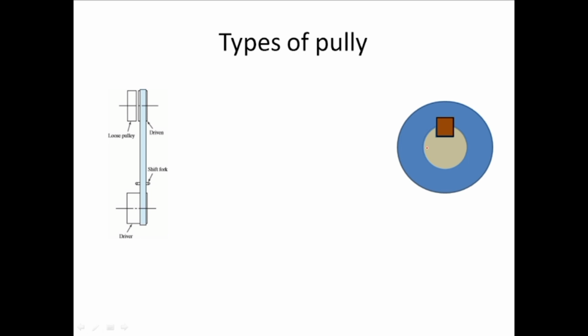After insertion, let's say when this shaft rotates in this direction, it will exert a force on this coupling key to rotate with itself, and in return it will exert a force on this pulley to rotate with it. So the pulley will rotate, and if this pulley is rotating in this direction, it will exert a force on this coupling key, which in turn will exert a force on this shaft, so it will rotate. So if we want a motion to be transferred from the shaft to the pulley, we should insert a coupling key in the groove, or we should have a permanent joint between the two.